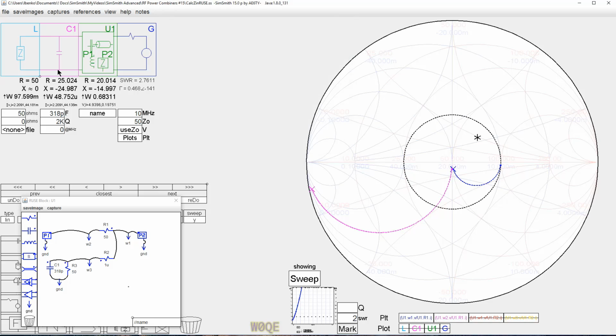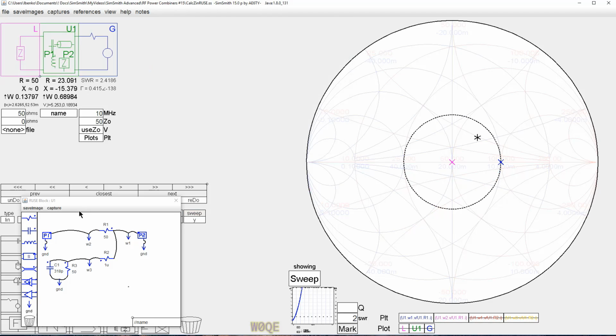So what we're going to do here is get rid of this capacitor down here. I won't get rid of it, I'll just delete the trace. And now what I see is the impedance when the calculation is done from here is 50 ohms. The impedance when the calculation is done from here is 100 ohms. So it doesn't matter what the resistor value is here. We just need to get the polarity right relative to measuring the voltage.